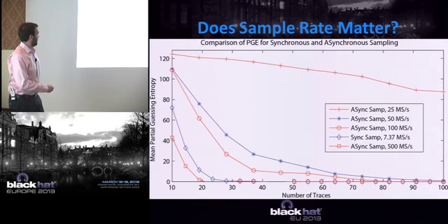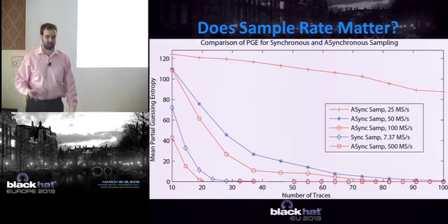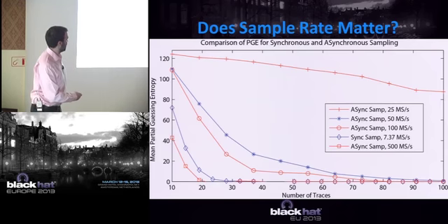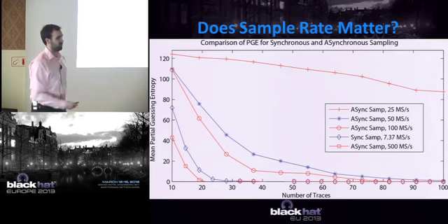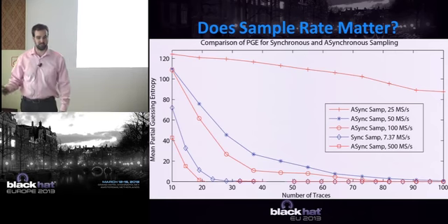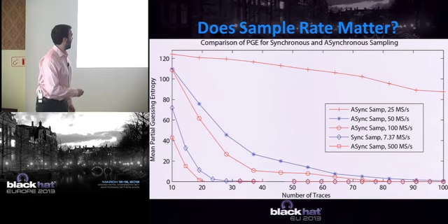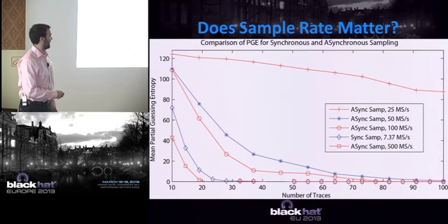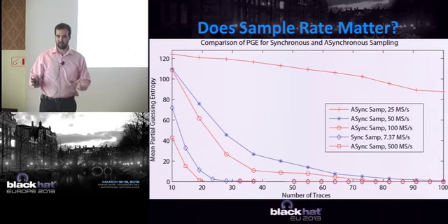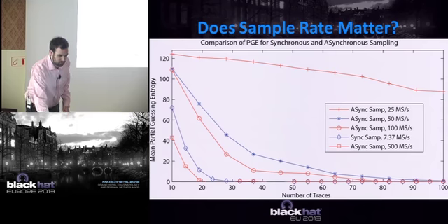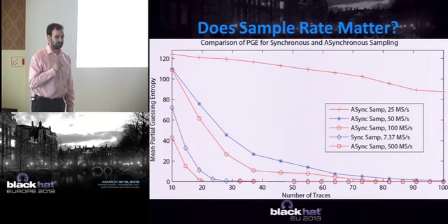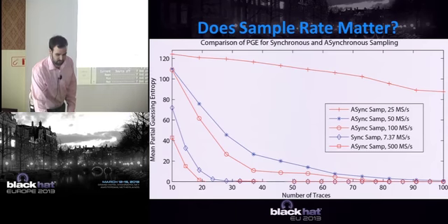So this line here, this blue line, is measuring at about 7.4 megasamples per second. At 7.4 megasamples per second, stuff's very cheap. ADCs are very cheap to buy. If you have to buy a 500 megasample per second ADC, not even talking about buying a scope, just the physical chip, even that is expensive. So by using synchronous sampling, you can greatly reduce your cost requirements.